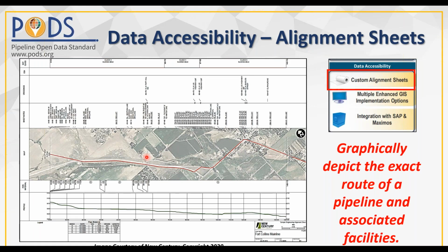So you'll see that the scale will oftentimes remain constant as the different sheets are generated. There's software available that actually will create alignment sheets for every segment of the pipeline. Put them all in order, get them into PDF format or whatever format that you may need.